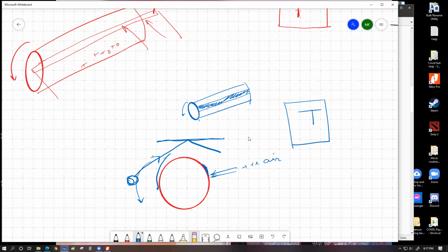Yes, sir. So as the light is sent, not all the light will fall over here, but some light will get reflected off the paper and eventually fall onto the selenium coating. This is essentially what we're interested in. If this is a light source and there is a barrier over here, this light source does not directly illuminate the selenium drum, because that would be entirely fruitless, no benefit.